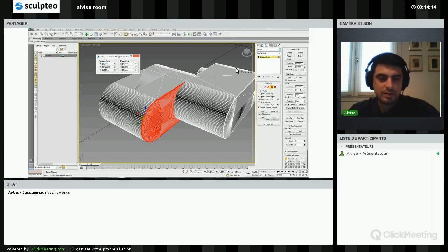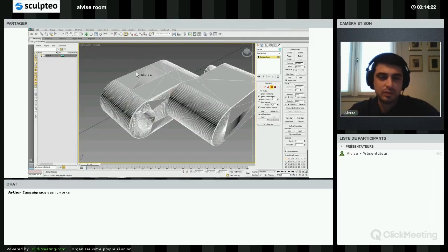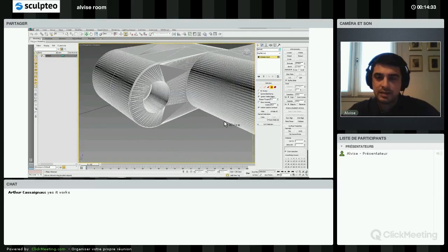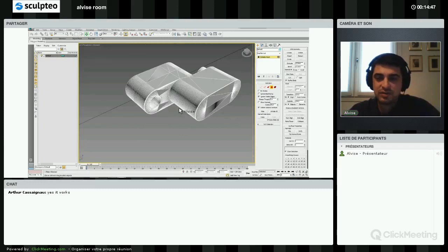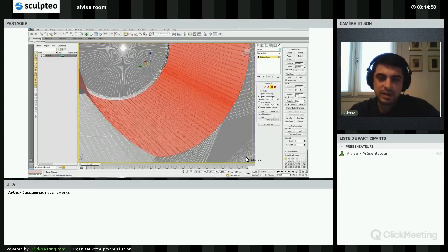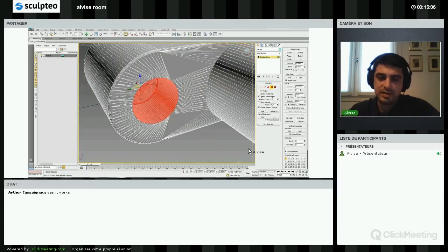Now what I want to do is make the inner cylinder bigger, 0.8 in diameter, to include the snap. You can see this other side of the part, and so again, polygon selection, keeping the same threshold that worked before, and select the part to scale just this part to a precise dimension. I need to detach it first from the rest, creating a second object. Select it, and now I have a separate object with its own pivot, so that I can scale it, keeping it in its center.